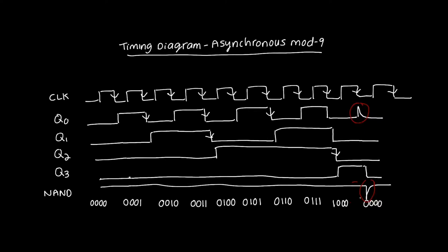So looking at the timing diagram again, we can see that when the clock has a negative edge, some short time after that, depending on the flip-flop, but in the order of nanoseconds, and usually not over double digits, Q0 goes high. And again, here at the next falling clock edge, some very short time after that, Q0 will toggle again.